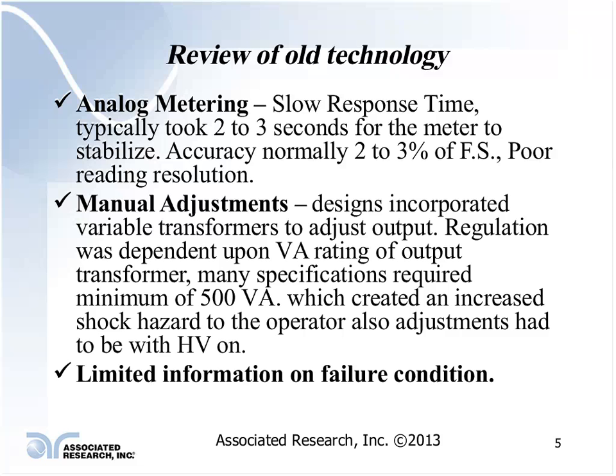If you're an old timer like me, we were using stuff that was made back in the 1960s era. A lot of the stuff had analog meters. One of the difficulties with those was a slow response time. Typical response time of an analog meter was anywhere from 2 to 3 seconds.